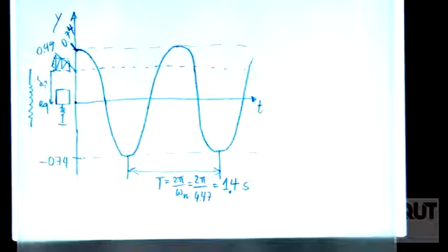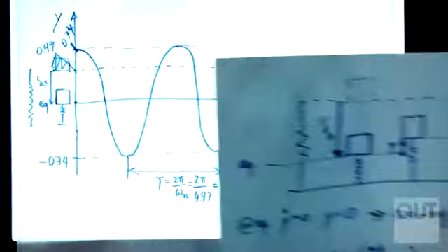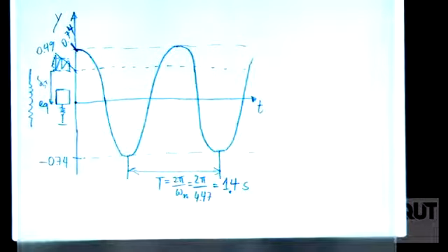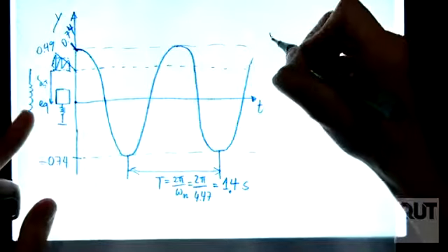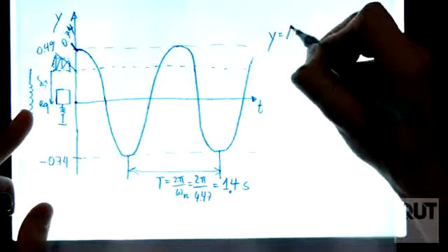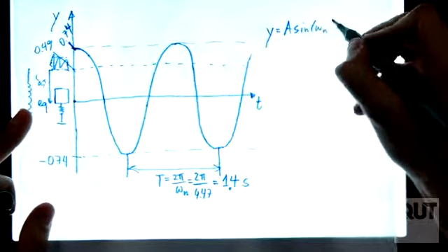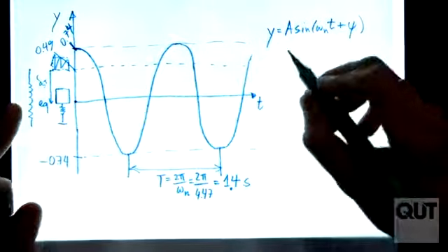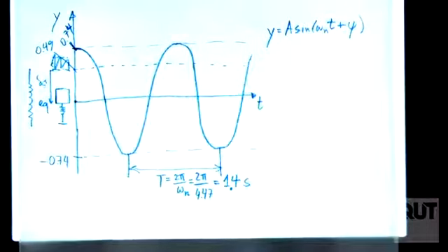Okay? So now you understand why I've said undamped vibration, undamped system. What does undamped mean? There is no damper. There's no damper in this system, obviously, right? There's only a spring. It vibrates forever. Why? Well, the vibration is a sine wave, A sine omega n t plus psi. If I take t even big, it's going to still vibrate. The sine wave never stops. Right? Agreed? Good.